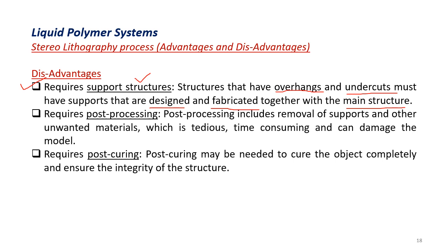using the available material itself. The next important disadvantage is the requirement of post processing. Post processing mainly includes removal of the support structure, unwanted materials, or any sacrificial layers. This is a time consuming and tedious job and can even damage the model if it is not properly removed. So a skilled operator is required to identify which are the support structures and unwanted materials, and which will not cause any damage to the model. Only those have to be removed. For that reason, caution has to be taken.